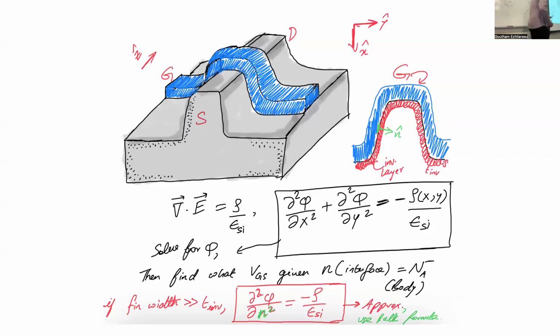So basically, this is the FinFET, right? So this is the source, and this is the gate, correct? It's going on top. So your question is, where is the lightly doped region, right? What you do is here you'll have sidewall spacers. So here there will be a sidewall spacer that will come like this. And so first, if you do a lightly doped implant, this region will be lightly doped, like over here, and this region lightly doped. Then you create the sidewall spacer, then you etch this down, and then you grow the silicon germanium here.